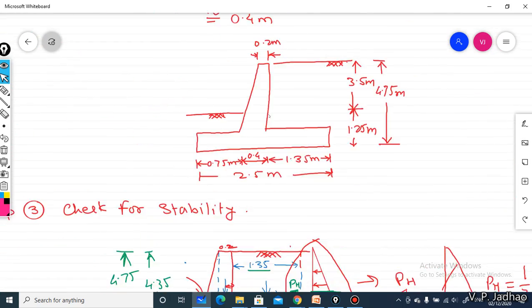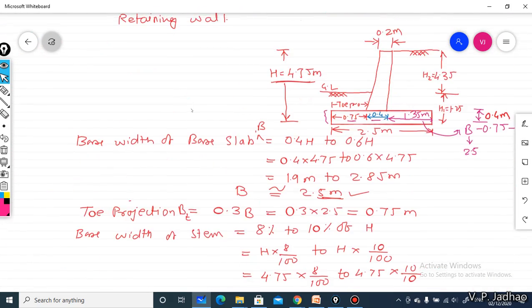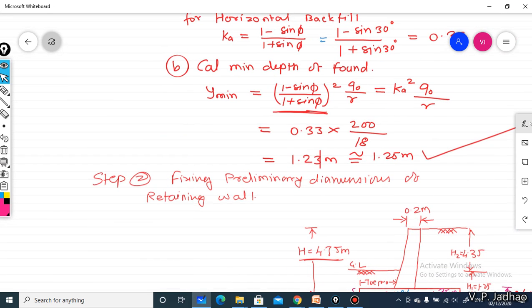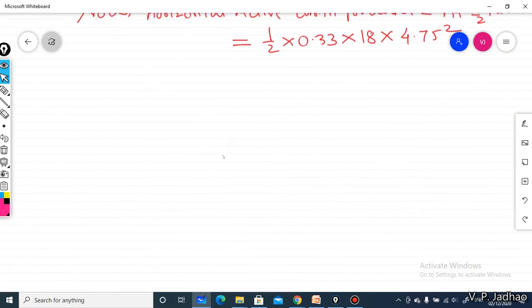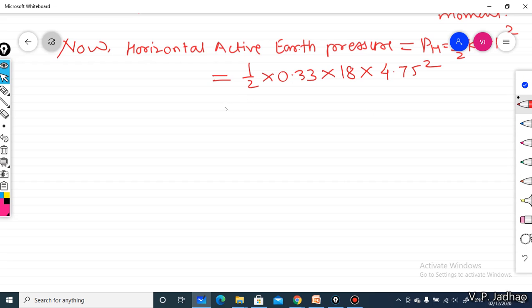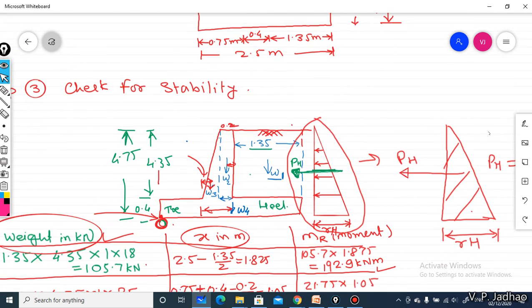Okay, there was some correction, I think. Here it should be 0.33 square, because this value is Ka square. By mistake I skipped that. Just keep in mind that. So this horizontal active earth pressure comes out to be 67.688 kilonewton, whereas this force will be acting at a height of...